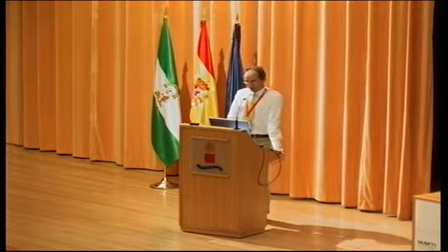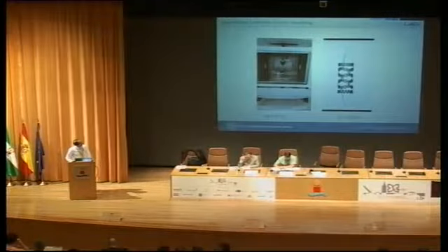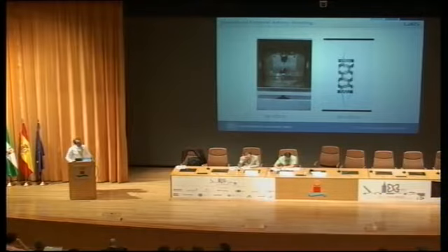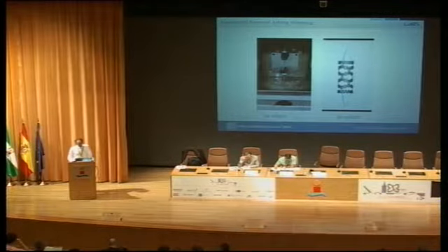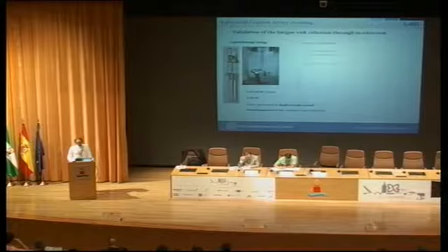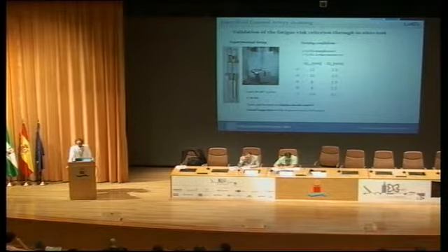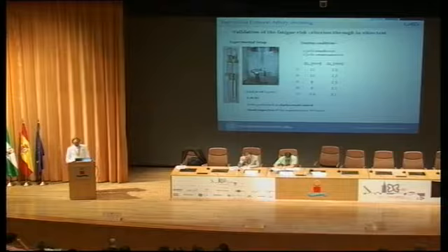So we ran some fatigue testing, and in parallel we also did some fatigue in silico simulation. And to verify the fatigue curve that we have identified, we ran a few examples, where we applied some tensile displacement, mean displacement and alternate displacement, and one was also done in compression.